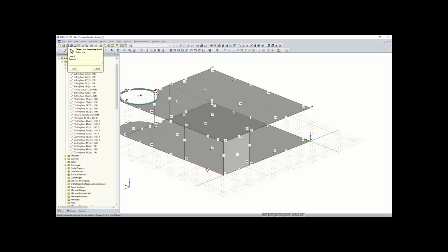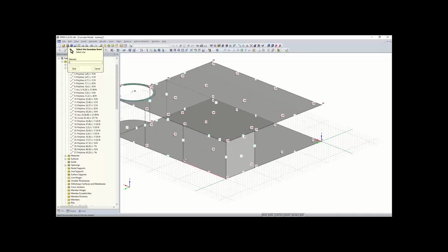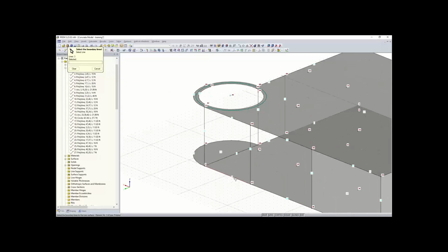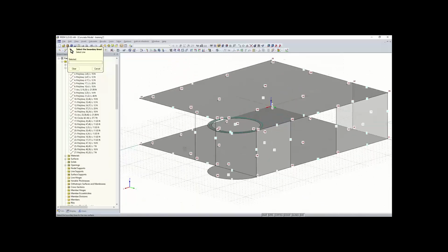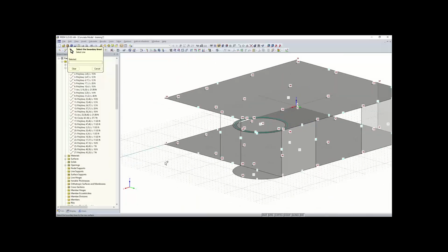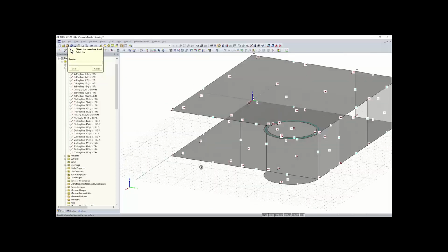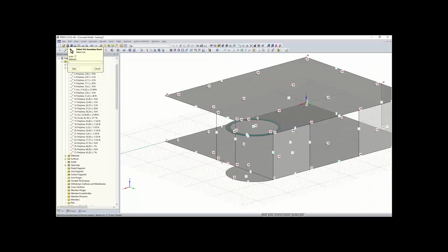And what that means is if I select this line, I can't just select the line above it. I have to select a connecting line and go around. I can keep doing this for the rest of my walls. I'll rotate the model. Another good hint for rotating is if you hold in Control and then right click, you can also rotate, which is nice. So I'll create these walls.